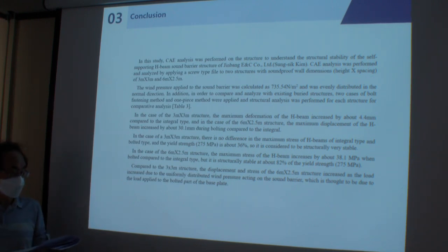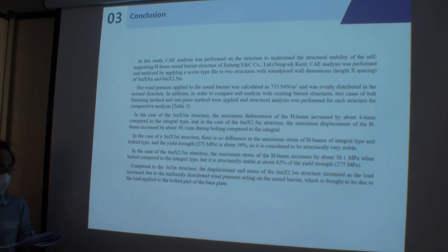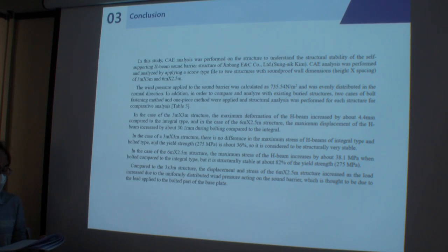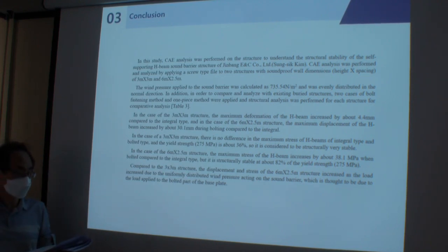In the case of the 3x3 structure, the maximum deformation of the H-beam increased by about 0.4 millimeter compared to the integral type. In the case of the 6x2.5 structure, the maximum displacement of the H-beam increased by about 30.1 millimeter with bolting compared to the integral.